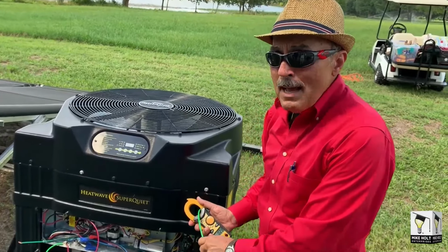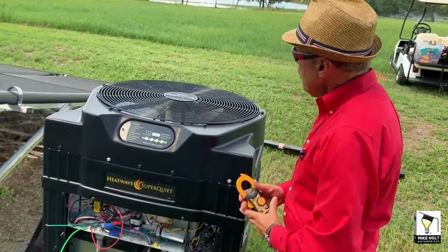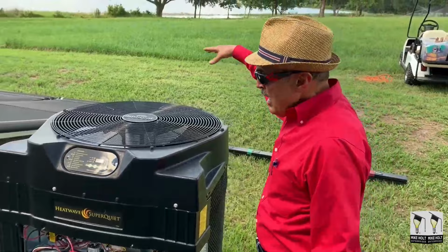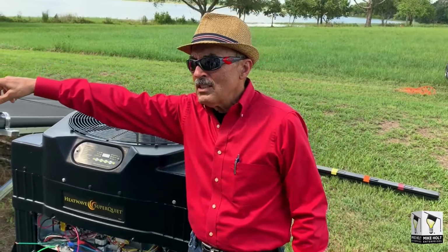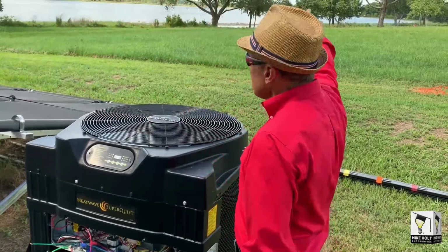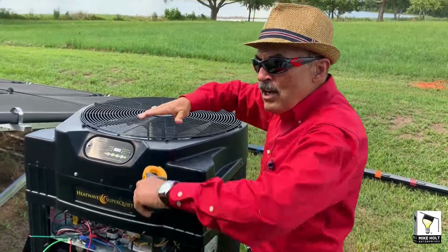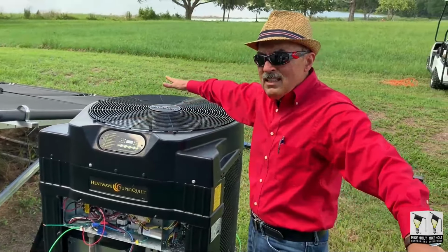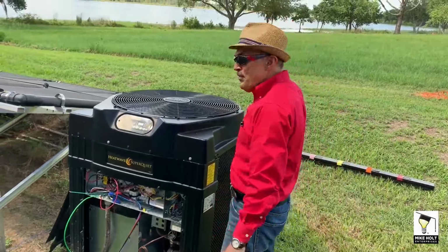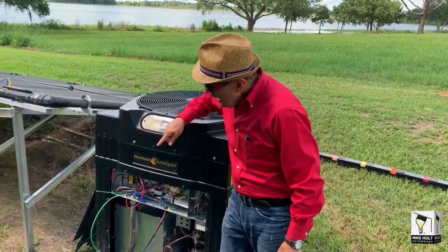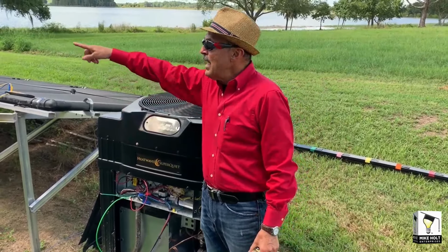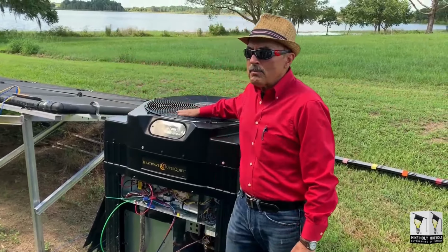Now but now watch what happens. Not only do you have this problem, but you have a ground rod over there. You have a piece of electronic equipment. You have a ground rod over here at the service. Lightning strikes the field. It creates a voltage gradient. Now the electricity will come up that ground rod through the wire that you installed, connect to the equipment over here, going back to the other ground and destroy your equipment.